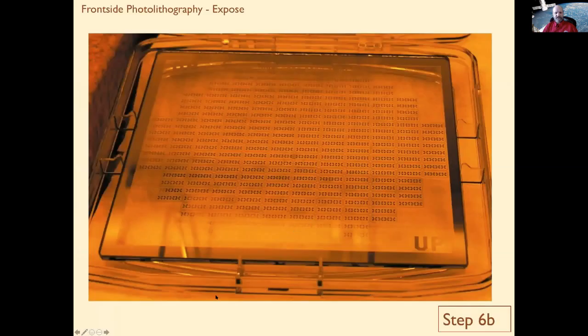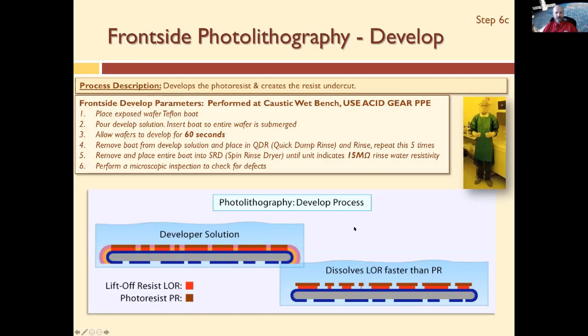All right, so this is what the front side mask looks like. Yeah, this is the Wheatstone bridge pattern. So let's continue on. We pattern the Wheatstone bridge, and we make sure it's aligned to the backside pattern. And then again, we have to go through the develop process.